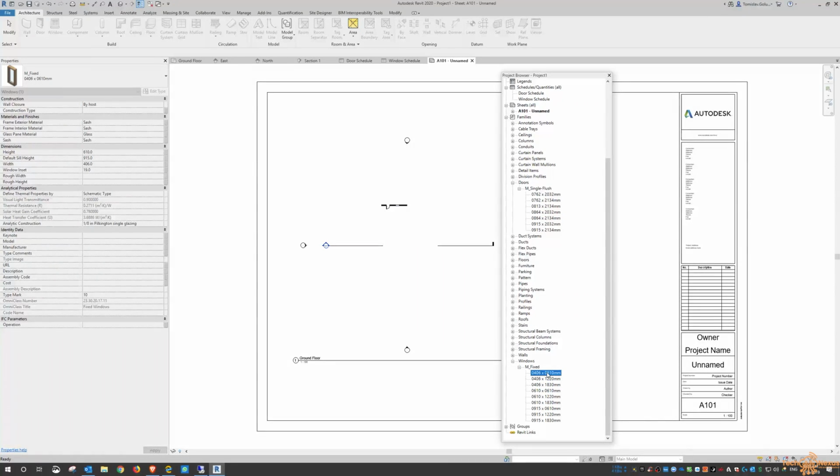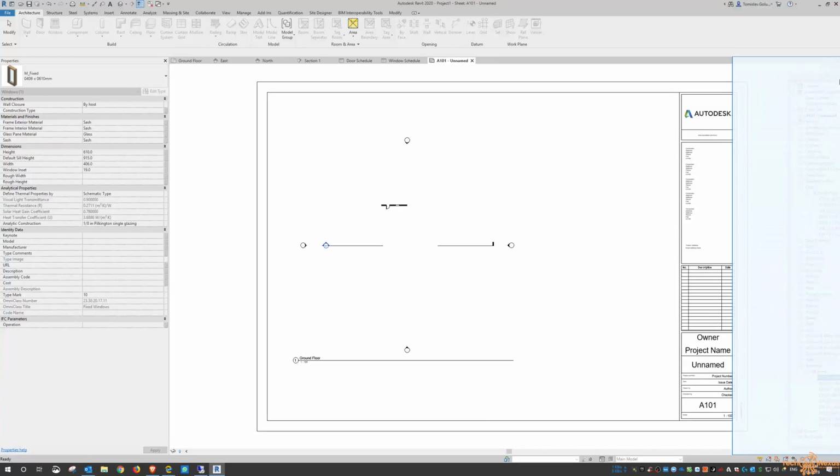It's never recommended to load too many families in here, just really only use the ones that you need. Otherwise you're going to start bogging down the file, and it'll get too big for the project. I'm not saying it'll be immediate, but as the project gets bigger and bigger, then you might start seeing performance issues as well. But Revit can easily handle, I've heard of files being a couple gig at least. So don't be too afraid to try and find its limits. It is good in that respect. So that's the project browser itself.